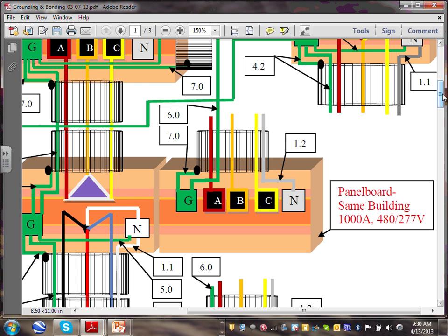If the conduit matches the hole right there, you can use the lock nuts on both sides, tight, to get you the connection for the conduits. So the best scenario, obviously, is we have a bonding bushing to attach to the pipe with a wire, and you attach it to the grounding bar inside your switchgear. That's typically what you do if you have an open bottom switchgear. If you have smaller panels, guys, there's a bunch of alternatives, like I said, for that method, exactly like at the service. Okay, number 7.